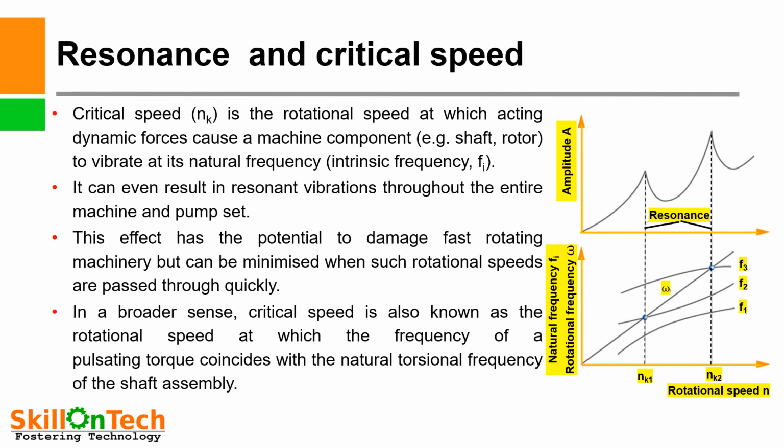This effect has the potential to damage fast rotating machinery but can be minimized when such rotational speeds are passed through quickly. So these natural frequencies shall be passed through quickly during the operation of the pump.